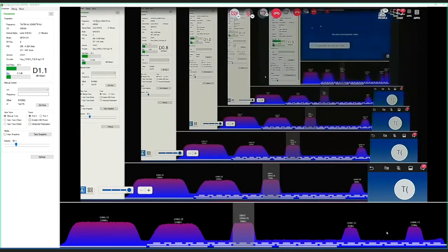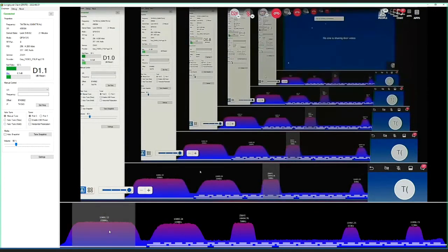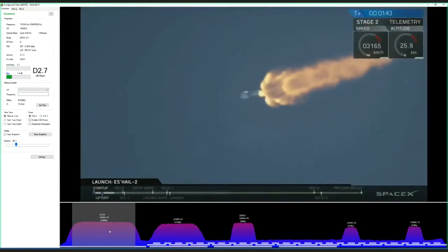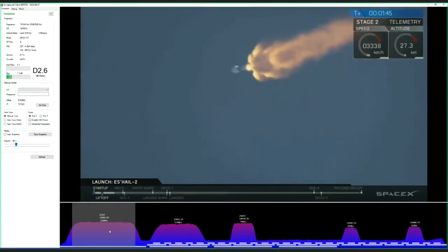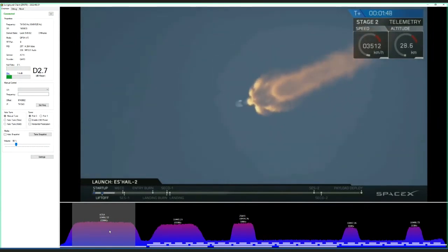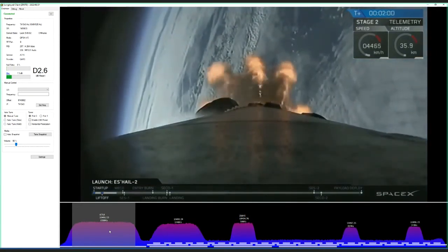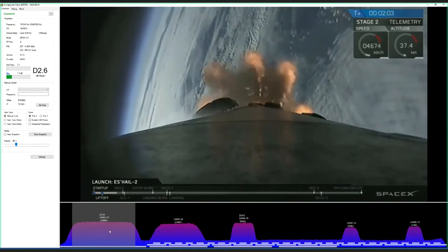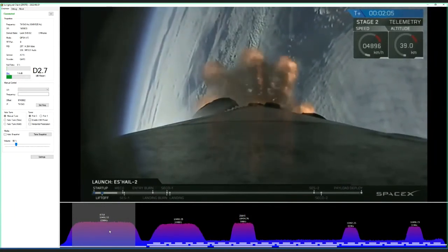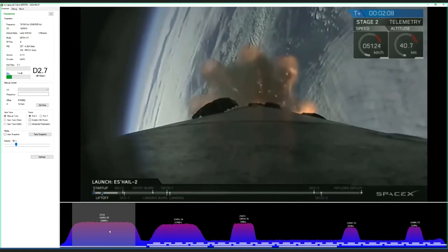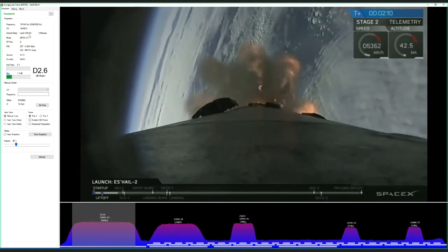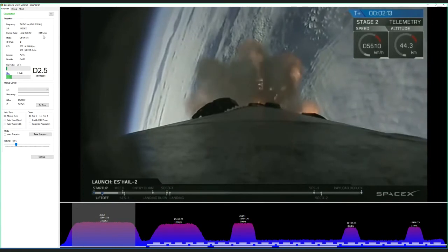So on the spectrum monitor below, you'll see all the different signals. So we can double click on the beacon, and that's the beacon that's currently running. The beacon is essentially a small video clip of the actual Falcon launch that put the SA Space, and then there's also some other bits and pieces in between. The beacon is a good way to align your dish. Once you've got a signal there, you tune onto the beacon, and then you start having a look at your received signal strength. And then we've got our various properties here on the top left side.